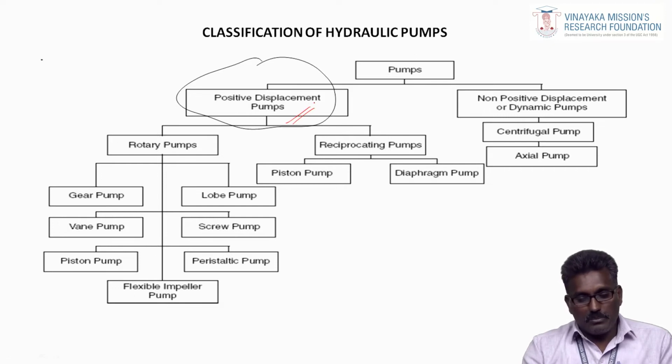These piston pumps are pumps you know very well. They are used in service stations for moderately pressurizing the fluid and cleaning vehicles. The diaphragm pump is also used for light to medium pressure applications, and mainly for fuel lifting. Take our buses and trucks: you know the position of the fuel tank.